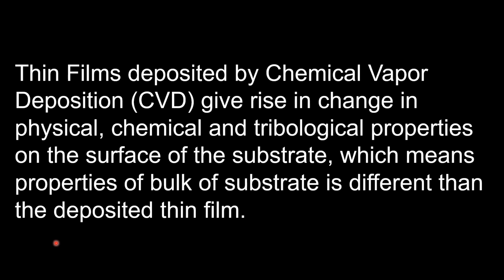But keep in mind, students, in order to deposit a thin film with the CVD process, you need to consider the lattice mismatch of the desired material with respect to the bulk material. If there is a larger variation of lattice mismatch between the deposited thin film and the bulk material, then there will be a stretching between the interfaces of the deposited thin film and bulk material, which will cause a defect in the deposited thin film.